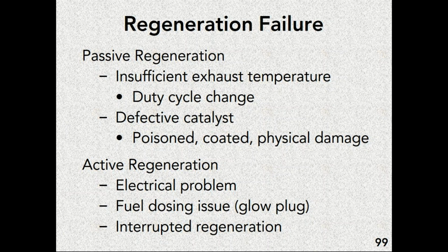But one of the things that can happen that is operator related is something called interrupted regeneration. It is fairly common for operators to not want to wait around for a regeneration to happen. The system says they need it, they start it, and they allow it to go only so long as they need to finish their job. The problem with that is that it will ultimately cause the filter to plug up before it should, because their interrupted regeneration has only burnt off a section of the filter media itself, and it winds up plugging beyond that.